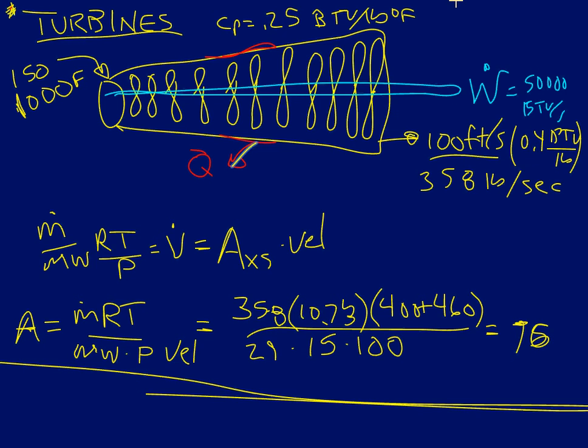Steam turbines operate similarly, but the thing about steam is that as it goes through this turbine and starts to drop in its pressure, it can get down to a range where liquid will start to form, and that can be a bit of a problem if you have little drops of liquid hitting these blades. But that's an issue. We'll look at that in another topic.